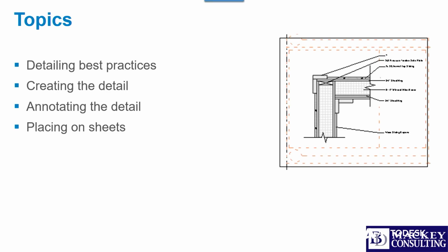So for me, I have a theory on best practices for doing details, and a lot of people look at me like I'm a little bit crazy when I start this. It's funny, I showed this to a client, I think in about 2006. They were making this great effort switching from AutoCAD. They said, look, we've created all of our AutoCAD details in Revit. And there wasn't a single detail component. It was all lines, filled regions, masking regions, and text. I said, that's great, how long have you been working on this? Like 4 months. I'm like, you did it all wrong.